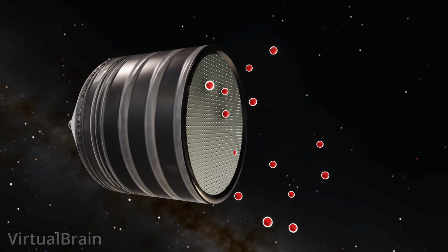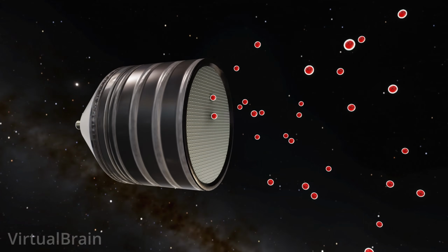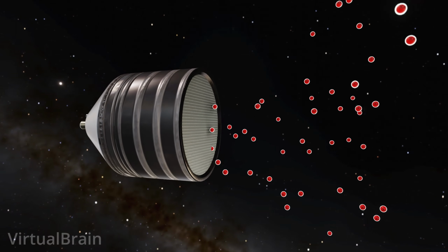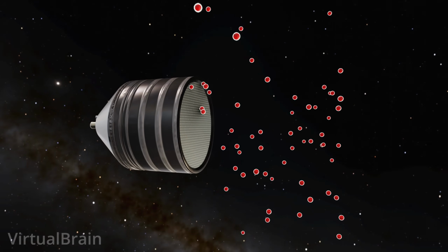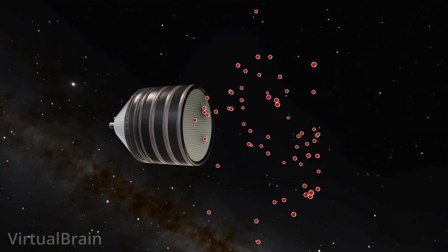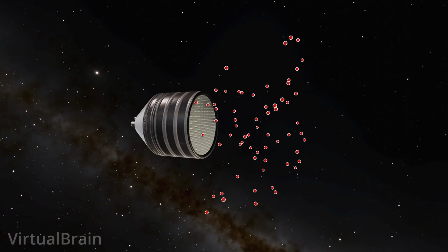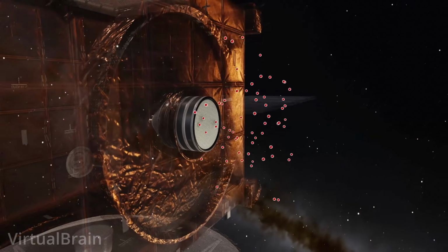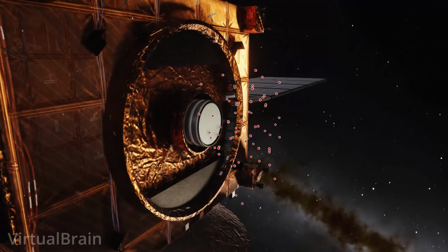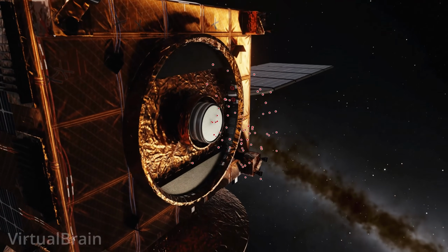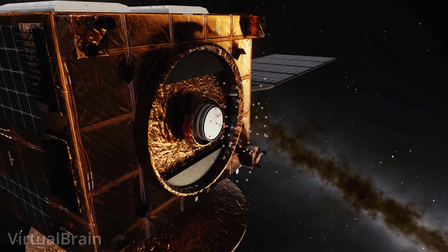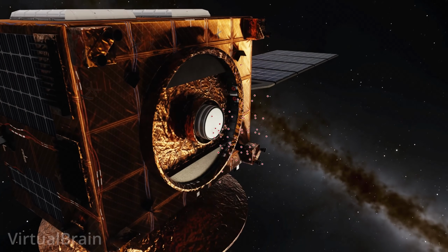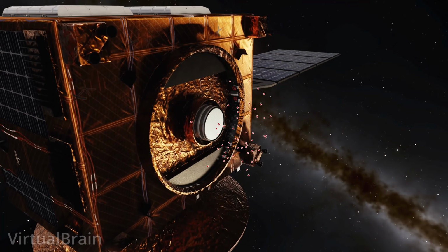While the xenon is being accelerated when it is between the two grids, once it passes through the second grid, the grid will begin to attract it in the opposite direction, partially neutralizing its effectiveness. Or xenon ions could even be diverted to other parts of the satellite that might be electrically charged and potentially interfere with its operation. Luckily, the solution is quite simple.